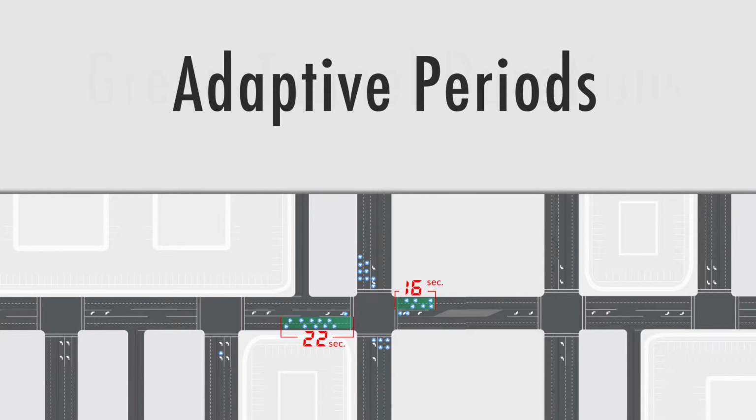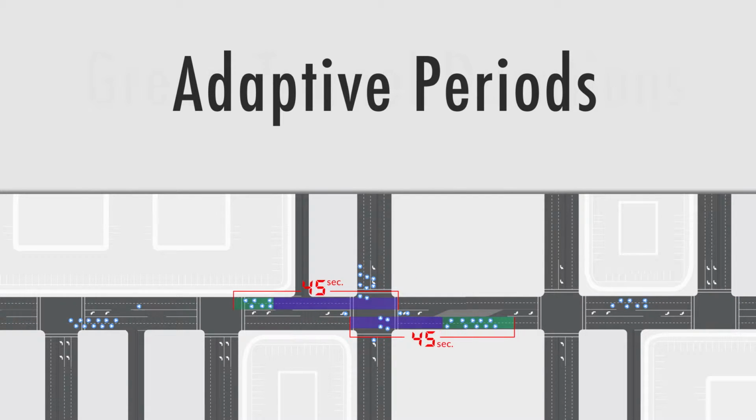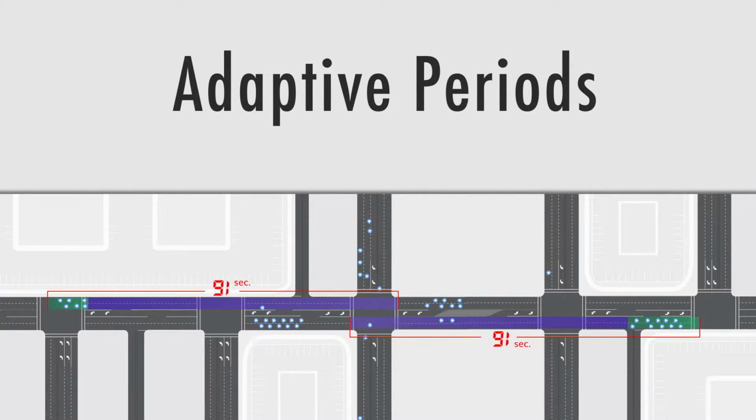Adaptive periods. Rhythm Engineering coined the term period for traffic operations to describe the time it takes to serve the green tunnel as well as dynamically serve all side street approaches at least once before the tunnel is served again, rather than only in a fixed cyclical order. In traditional responsive signal timing, each intersection serves its traffic in fixed sequences, which drive the intersection's ability to bidirectionally coordinate traffic. InSync does not use cyclic operations, which limit bidirectional progression in a network of irregularly spaced intersections.